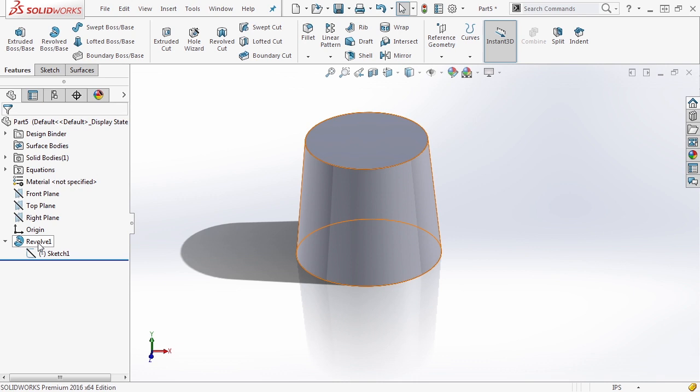Now it's not limited to revolve. You could still do things like loft from one boundary to another and make sure that you have the available draft. And if you take a look at the other course on creating molded parts, I go into some more specific examples of using things like surfaces and helper surfaces to start creating very organic complex shapes by using initially a sketch that is a draft, essentially at a draft angle, to create those files.